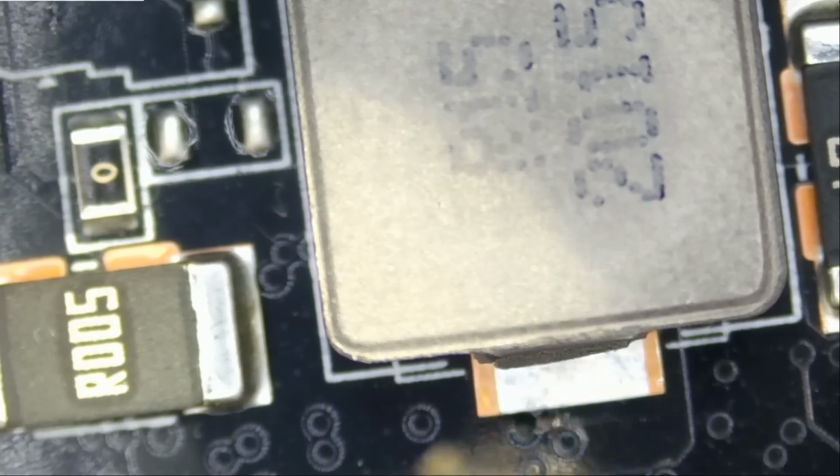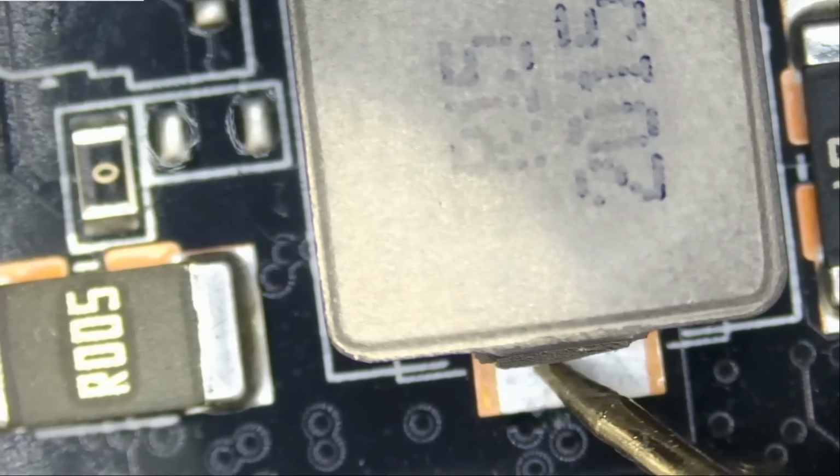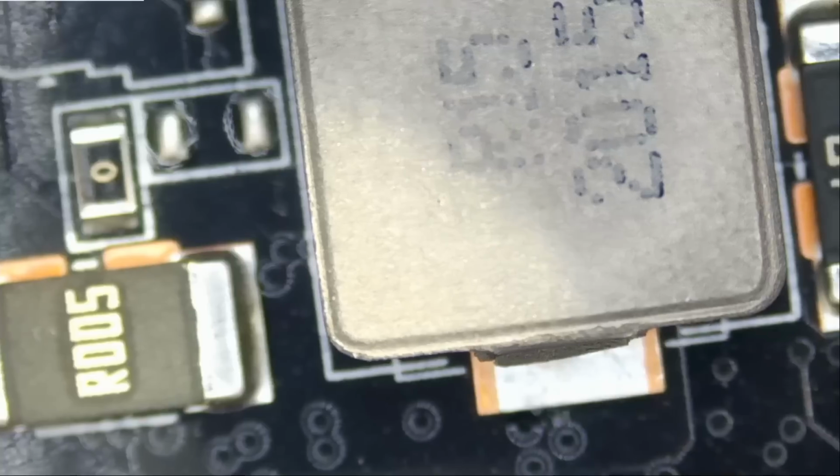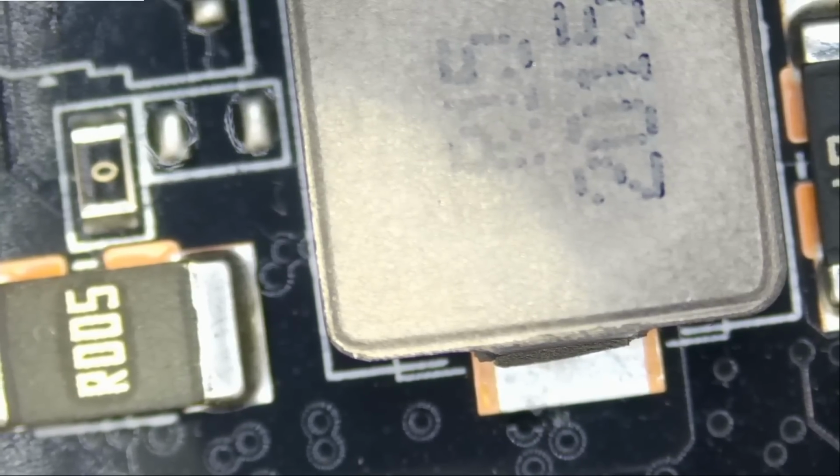So what happens if we inject voltage right here? I'm injecting 1.2 volts, and amperage being drawn by the board is 1.76. Let's see if we can see that heat on the thermal camera. Heat sometimes is very minimal because the board is multi-layer. It absorbs heat, and it makes it difficult to pinpoint where the heat is coming from. In which case, we may have to increase voltage in order to see any heat on the board.